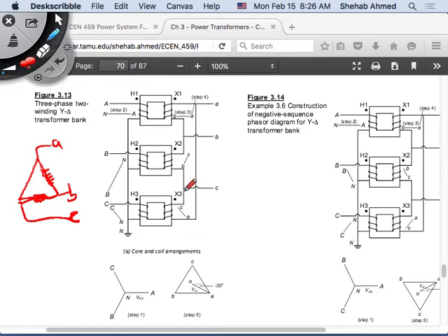And then C is connected one side to the winding between it and phase B, which is this. And then there's another winding between phase C terminal and phase A, so that's this one here. Okay, so this is the connection on the secondary side as a delta.